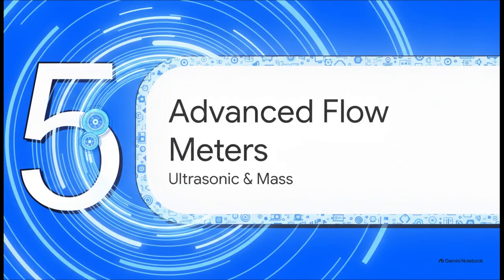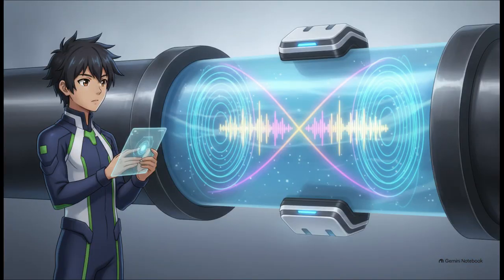And that brings us to our final section, Section 5, ultrasonic and mass flow meters. Let's see how advanced electronics measure flow. Ultrasonic meters are just incredibly versatile. They operate by measuring the transit time of sound waves crossing a pipe. And the best part, because they often just clamp right onto the outside of the pipe, they don't obstruct the flow at all. They can measure everything from large factory conduits and thick industrial slurries all the way to literal massive open ocean currents. They just transmit high-frequency sound through the moving liquid. Basically, if the fluid can transmit sound, an ultrasonic meter can usually measure it.